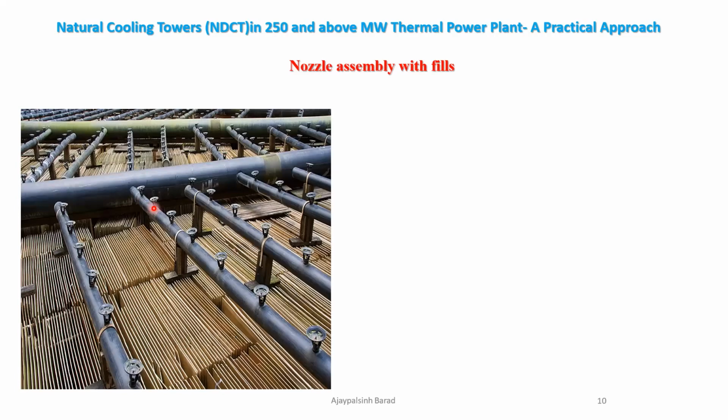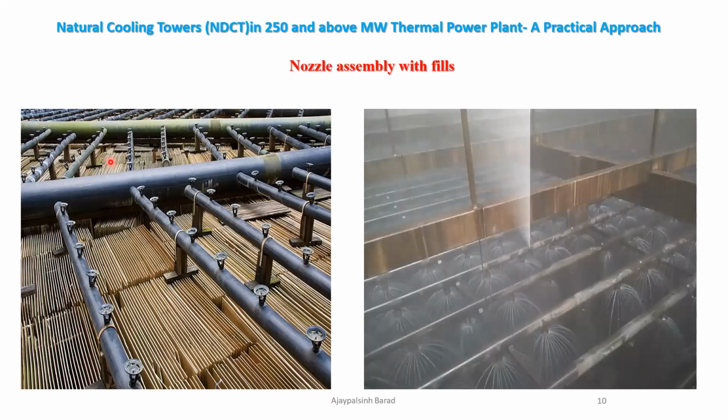Because the water is coming with pressure, the water flows out of the nozzles and falls on these fills. These fills are of different types, as shown here. Actually, the ones where I worked were polypropylene or plastic material.